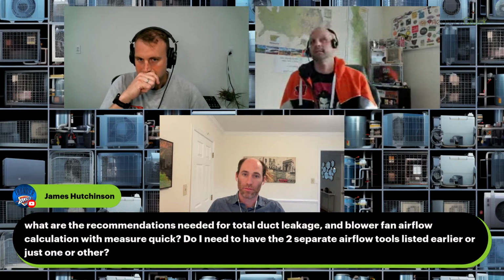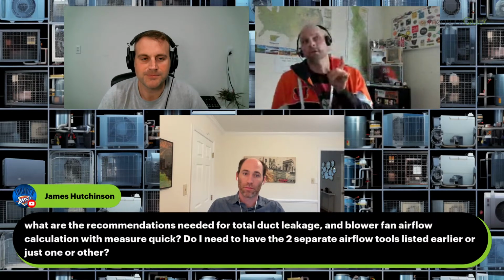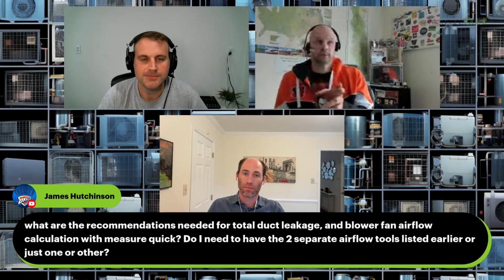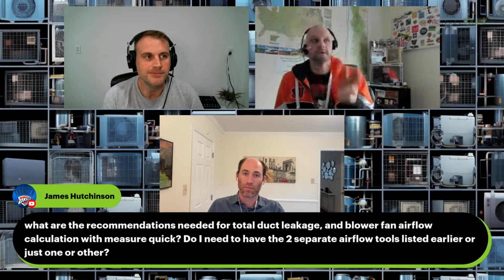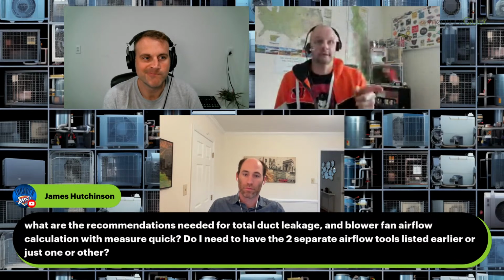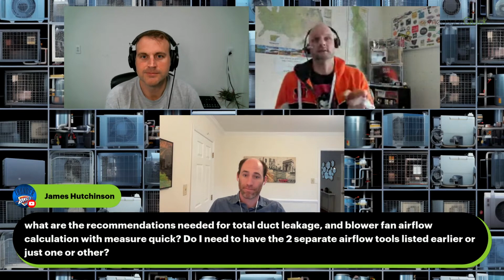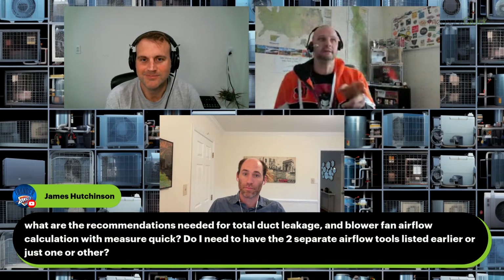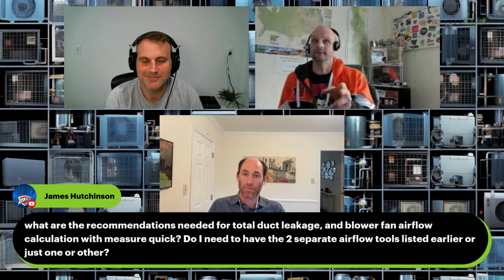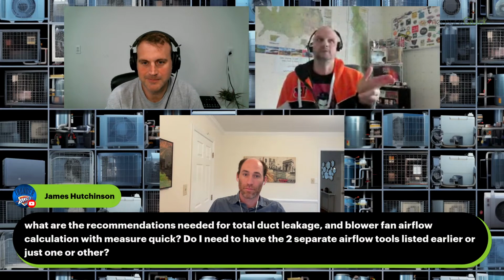I will add this though, just in terms of the question here. In terms of 310 and the workflow and what's allowed and not allowed, you can use your duct tester to measure duct leakage, and then also use your duct tester as a pressure matching device and use it to measure airflow. But here's the caveat with that. The duct tester is only going to get you to about 2 tons. And then you're going to have to do something else. So there's no reason to not own the TrueFlow meter.